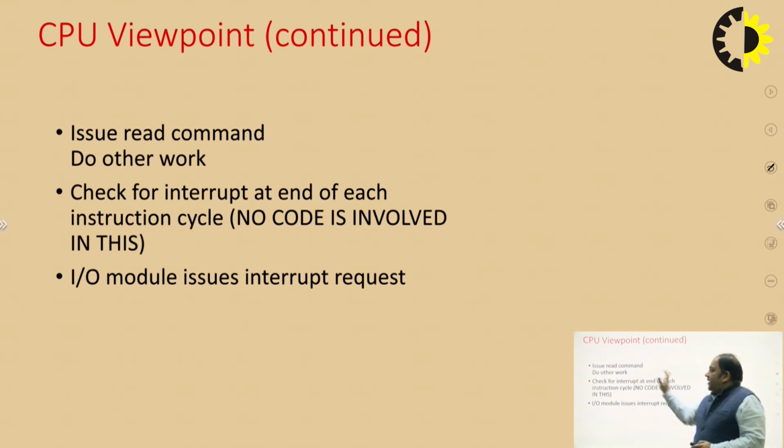The CPU issues the read command and starts doing some other work. It checks for an interrupt at the end of each instruction cycle. In the interrupt input output mode of transfer, there is no involvement of code. All work is done through interrupt signals.